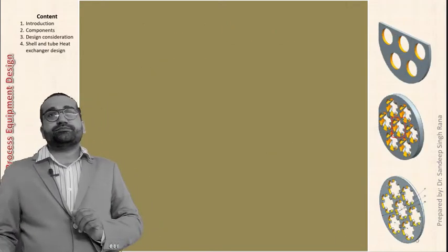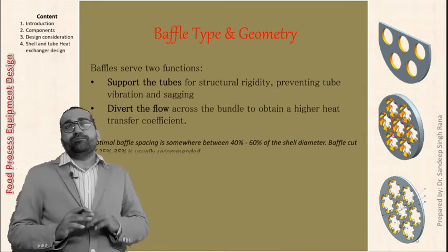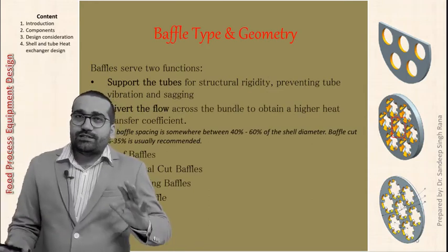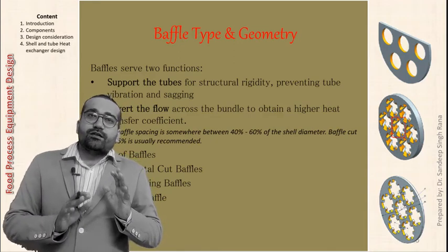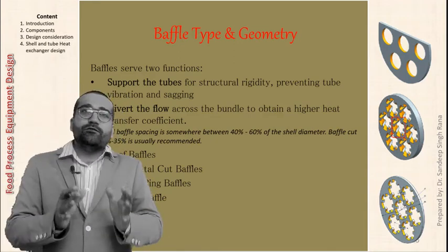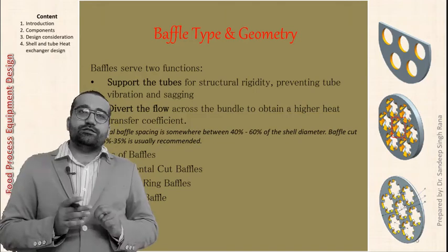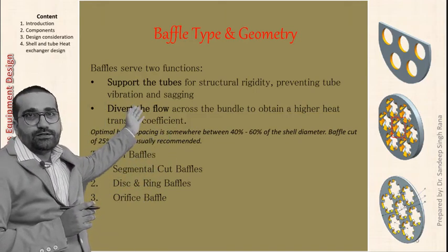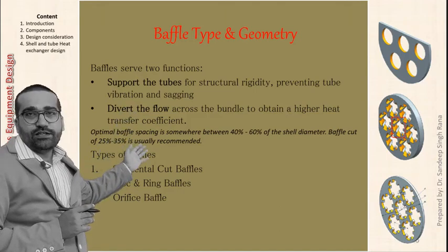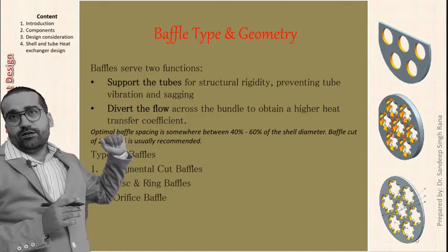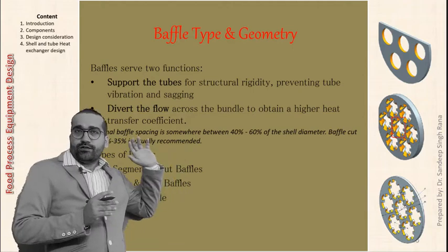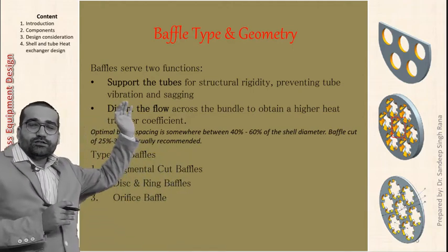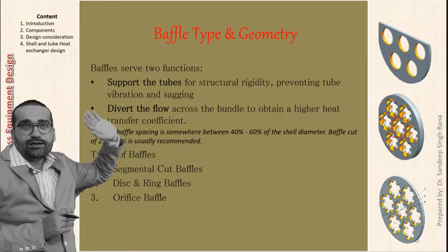After this, let's talk about baffles. So baffles are the components which perform two functions. First function is to support the tubes. Second one is to divert the flow. So a part of the support that the head plate or end plate gives is given by baffles also.